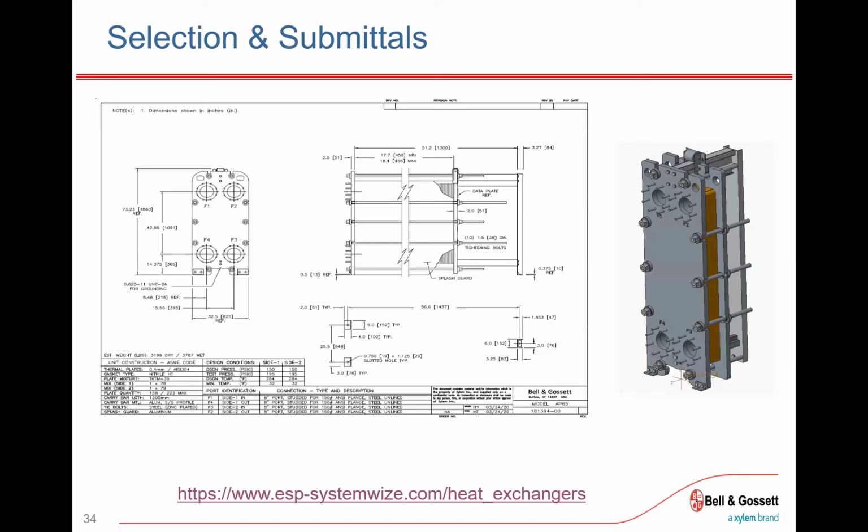So I'm not aware of any benefit of the same direction, that parallel flow. We want to have that counterflow. That's going to give us that greatest LMTD, which is going to maximize our given surface area. If we wanted to achieve the same heat transfer and you had one parallel, one countercurrent, with everything else held constant, you would require more surface area for that parallel flow.